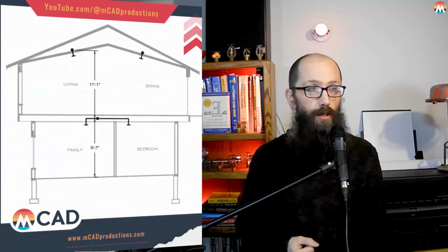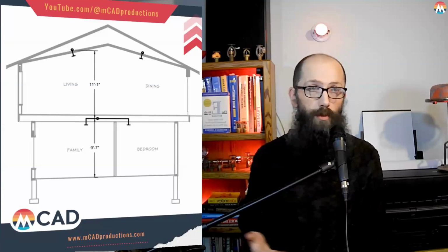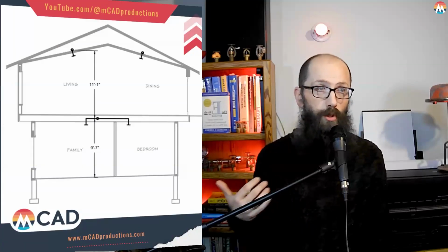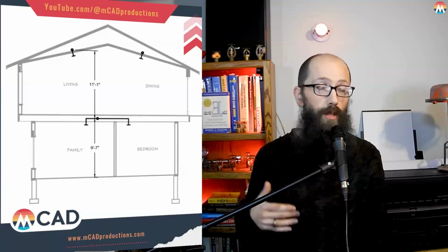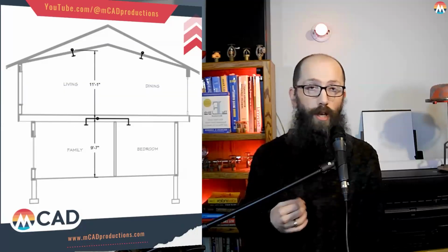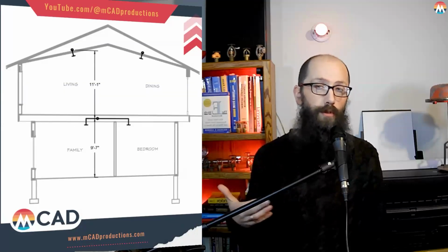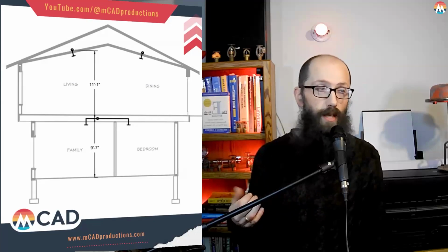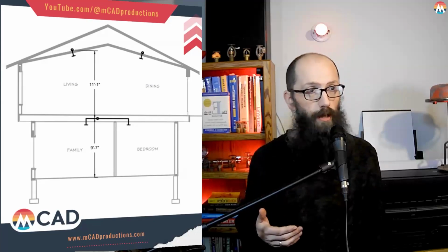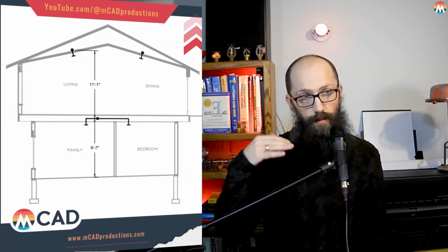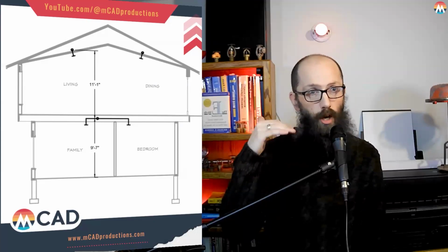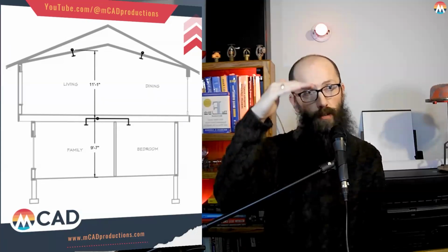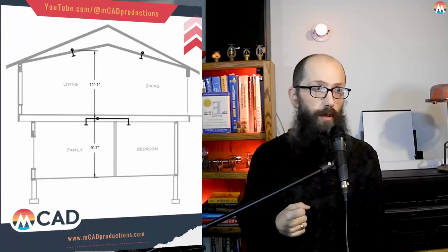Well, here's another project. This is a 2-story home, and this is what we're talking about. We're showing the elevation difference between the piping floor to floor. And again, this is helpful to the plans examiner when he's reviewing the hydraulic calculations, because our biggest pressure loss is that elevation going up from floor to floor.